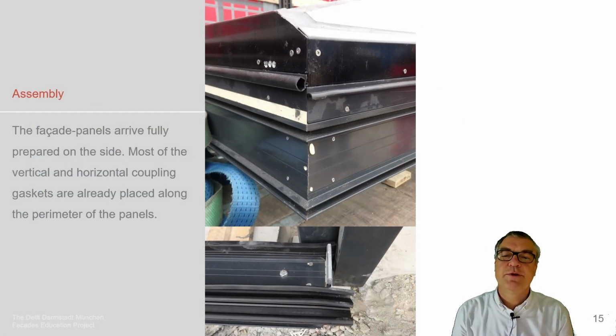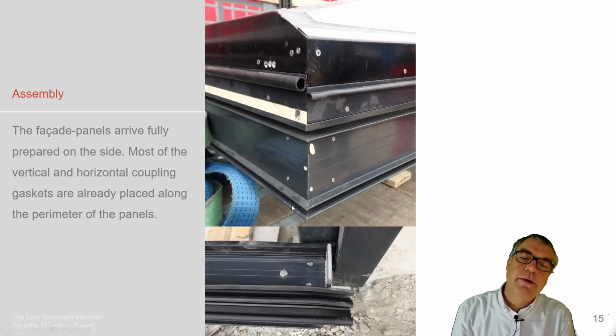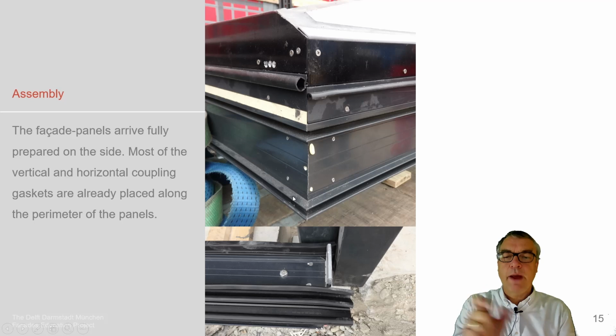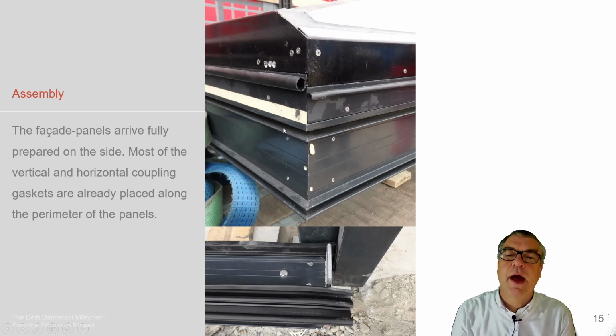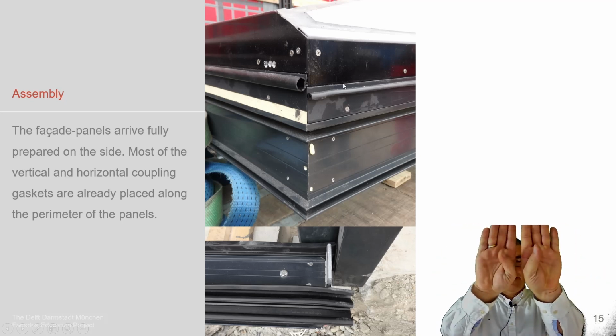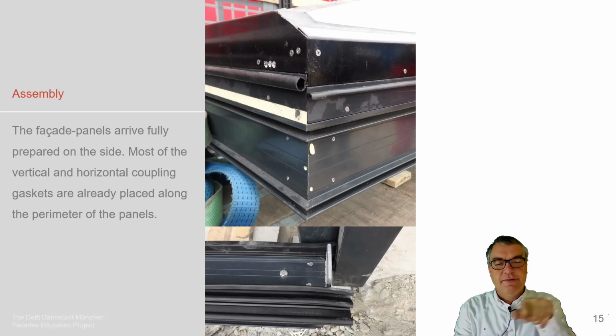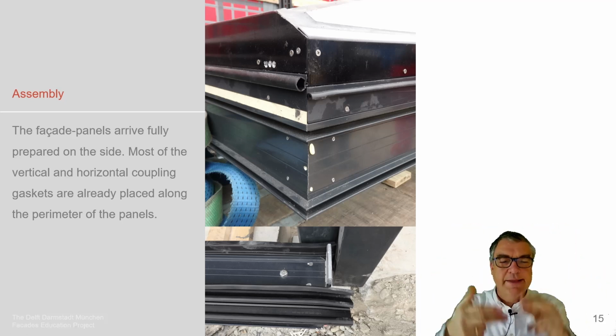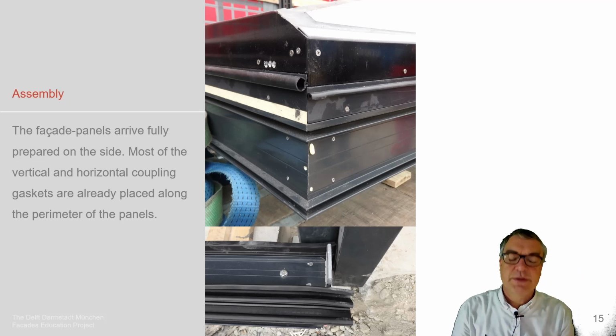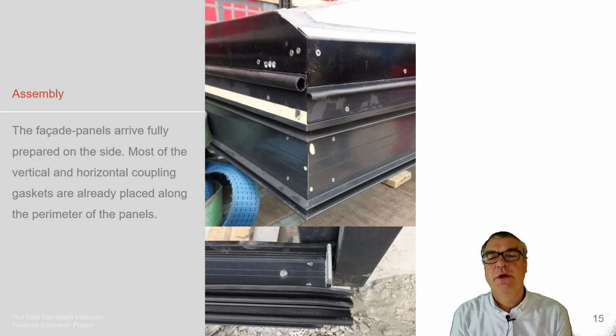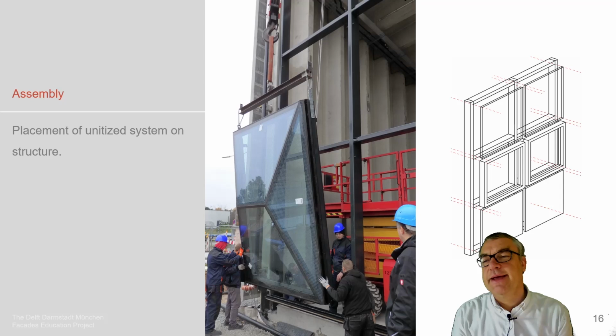These are the profiles, and we see the inner rubber to be positioned in here. We see the inner, outer rain-tight rubber, and here we see the final outer rubber being brought in position. And you also can imagine that the joint, so we have one of that here, one of that here, and then this middle joint where all the four lines are coming together, that's always the most interesting one, to make sure that the rubbers really find their position nicely.